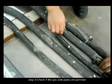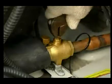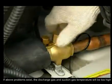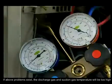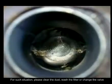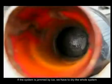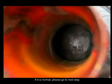Step 3. Check if the gas side pipes are jammed. For example, the pipe is deformed, the electric expansion valve is jammed, the low pressure ball valve is not open, or the filter is jammed, and so on. If the above problem exists, the discharge gas and suction gas temperature will be too high, low pressure and current will be too low, and the suction pipe may be frosted. For such a situation, please clear the dust, wash the filter, or change the valve. If the system is jammed by ice, we have to dry the whole system. If it is normal, please go to the next step.